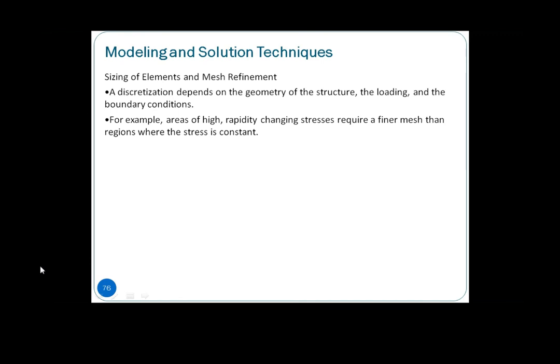If you are looking more towards global movements or global types of analysis, here talking about probably displacement, where the whole structure is moving together subject to that loading, then probably the mesh sizing, or the number of elements, does not need to be so refined.